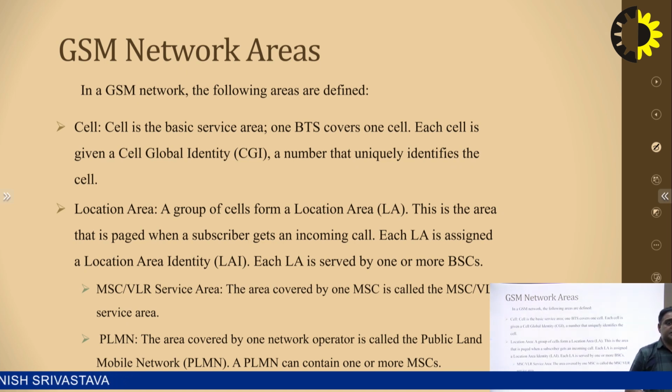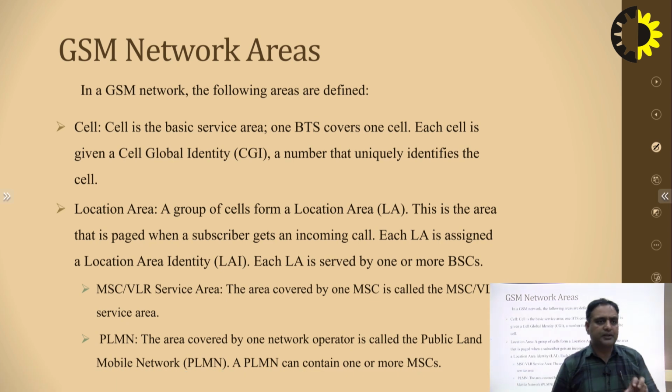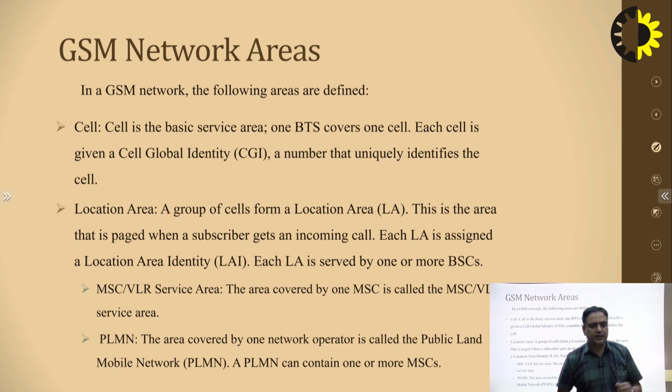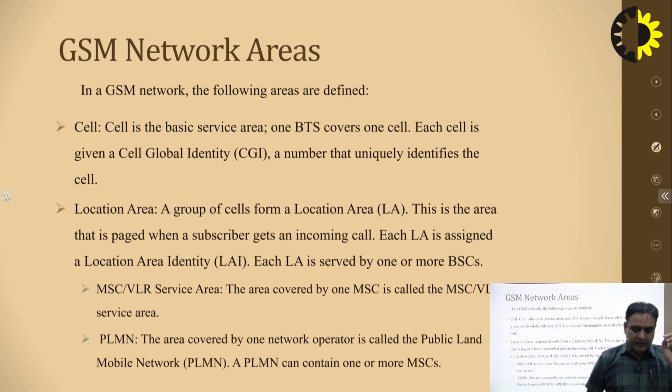Each cell, each GSM antenna, has a cell ID. The RF engineer working for an operator gives a unique cell ID to a BTS. A BTS has 2 or 3 GSM antennas. So one antenna means one cell ID, and this cell ID has to be unique.